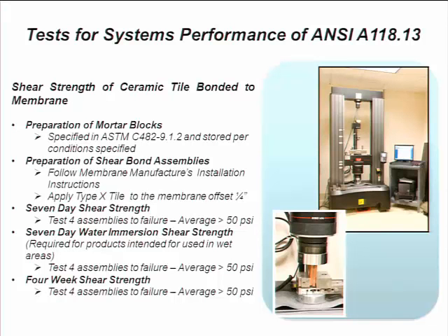Looking at preparation of those shear bonds, they have to be prepared with an offset because what you'll see in this machine, in this particular case an Instron, is that the assembly will be set up in the Instron, and after it's cured the proper amount of time at the proper temperature, you will conduct a shear because you also want to know what is the bonding capability of that tile to the membrane. Not only are you concerned about sound, but you're concerned about the performance and longevity of that installation, and the bond is a critical consideration that is aligned with the specification.